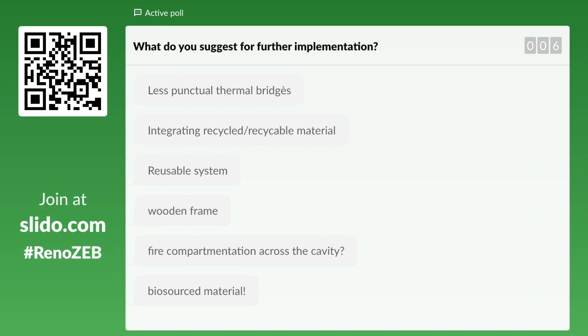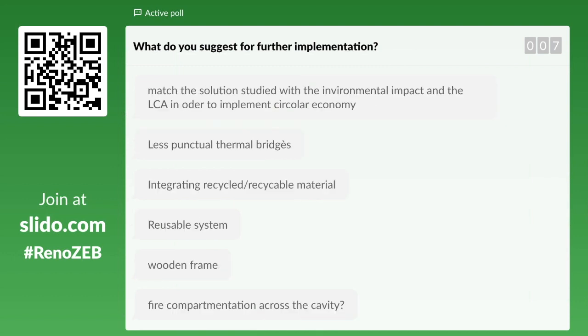In the case the cavity is not used for additional insulation, we can position specific mineral wool as a fire stop in front of the slab, between the chains of the unit. Usually that is the position where we install the compartmentation.